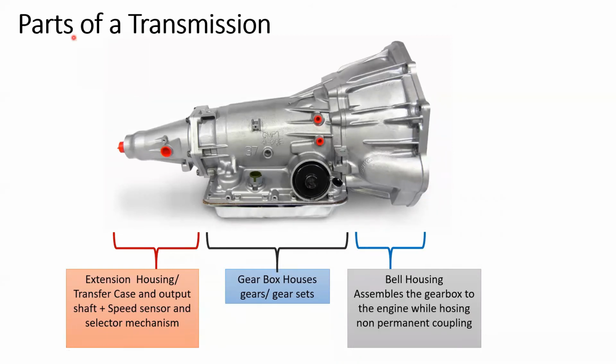I teach this every time; even your seniors, I recently also discussed this part. Transmission and gearbox are 2 different things, right? Usually we call this whole section the gearbox. That's wrong. The gearbox part is only the middle section. This is the gearbox, right? And this is called the bell housing, right? The engine comes and connects over here.